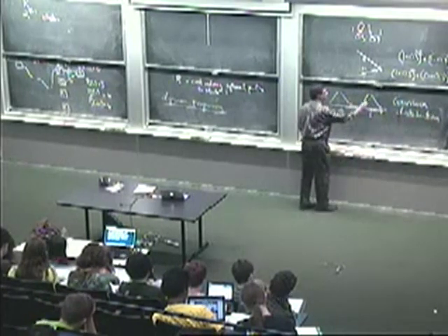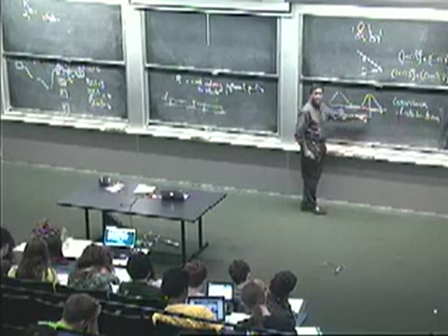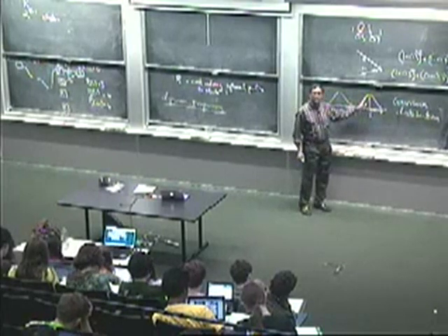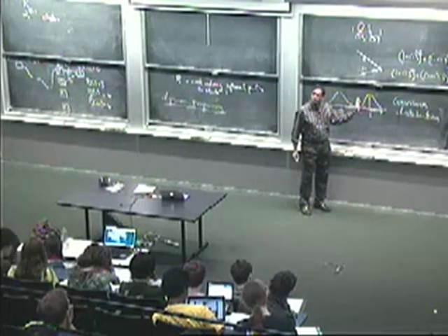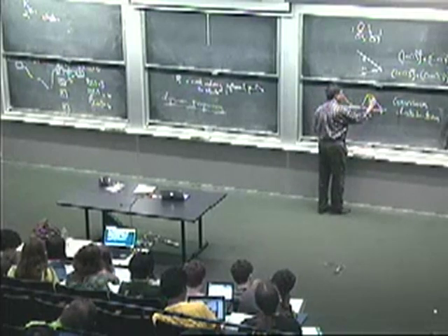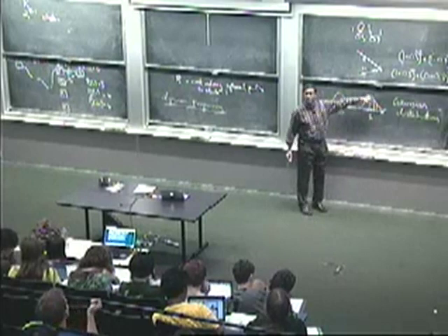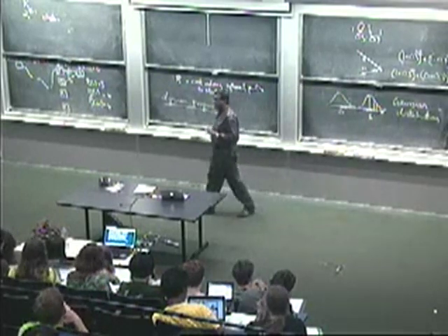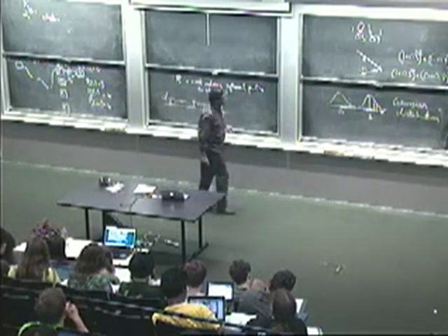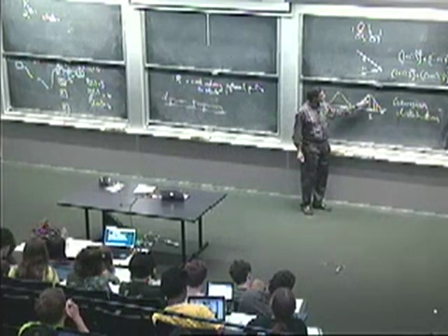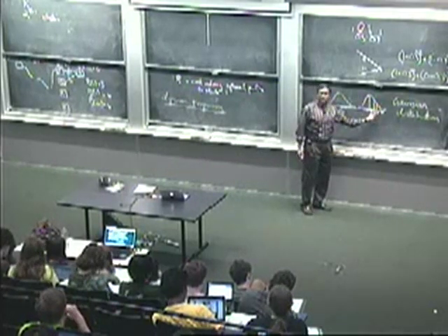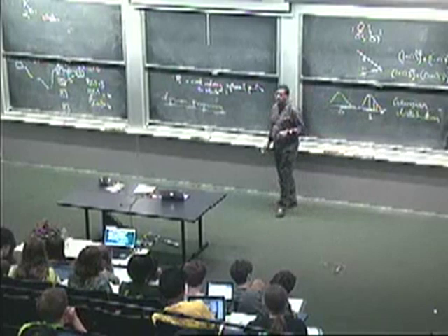So what we're saying is that if you send a 1, you get a spread of possible values. The probability of your values falling in some particular range here can be computed by the area under this particular curve. It's got an analytical expression. So this is the most likely spot, but there's certainly probabilities of falling in any particular interval here.